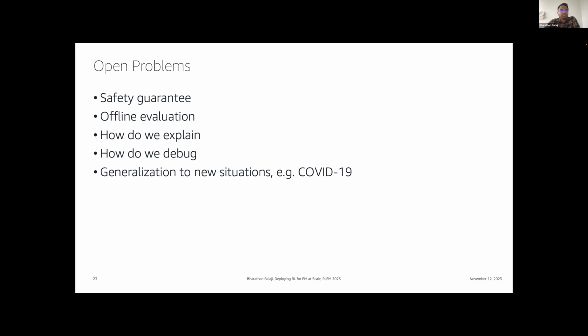Yeah, model-based, so if we are going to the simulator-based model-based, then I kind of covered that, but model-based as in data-driven models, then distribution shift is the main focus. If you're going to change the conditions in that thermal environment to be far different from historical, then how do you account for distribution shift in your data-driven models? So that is a pretty big challenge and not easy to solve. We do solve that in some other context, but it's a fairly open problem when it comes to building controls.